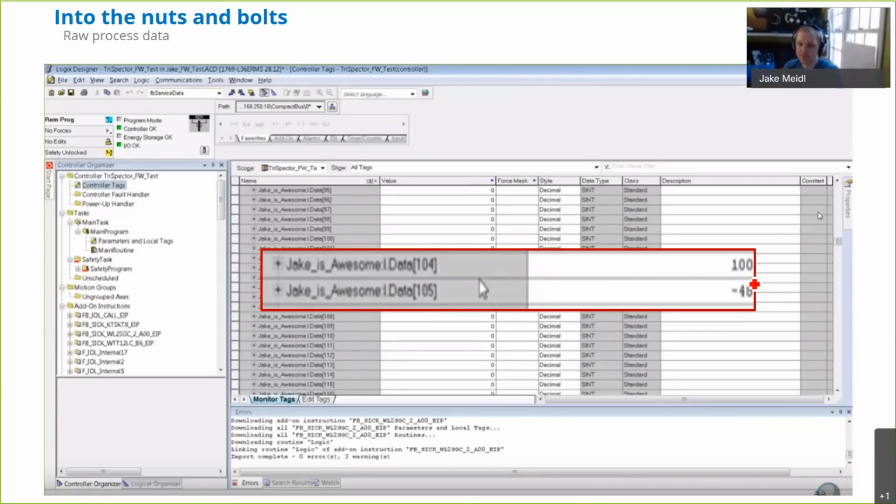Here we can expand the actual bytes that we're looking at. So this is 104 expanded to see the individual ones and zeros. This is where we start to get close to what we're looking for here. Ones and zeros, what do those ones and zeros mean? Now this is where we take a step back and we look at our sensors, the sensor you have connected, and let's look at its process data, the information that it's putting out to this IO-Link master, to the PLC.